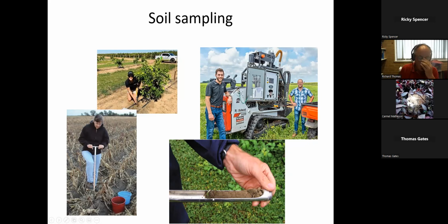If you want to sample and work out water holding capacity, you can't do it with these. You'd have to use a bigger diameter corer, literally like a cake cutter, for cutting cakes or pastry. It's a circular thing that you take a plug of soil with, about 5 to 7 centimeters in diameter.